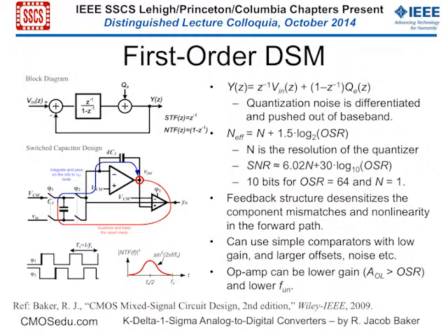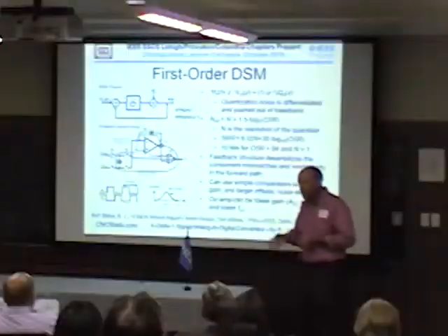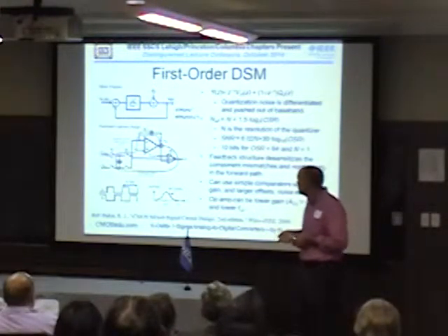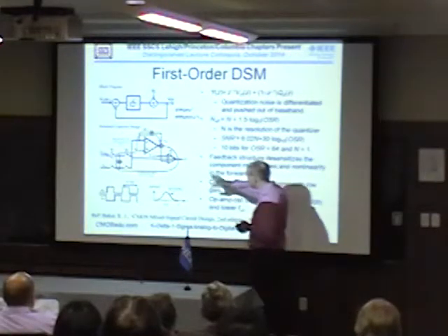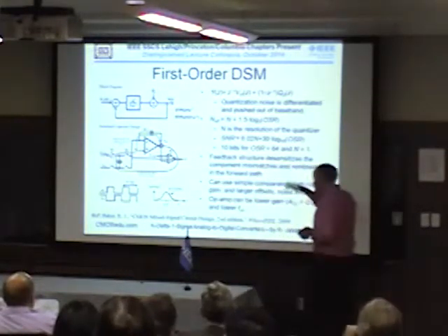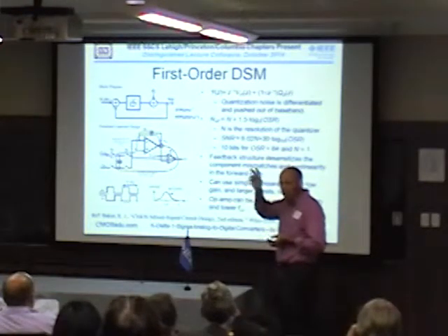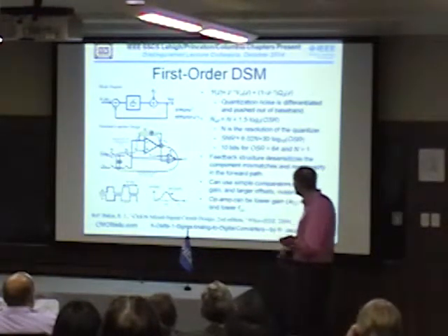And you could also do the analogy, if you wanted to be quicker, is you're going to either add a cup of water or you're going to remove a cup of water from the bucket. Okay, and so basically that's what this is. Okay, so your output code is 1010. You maybe change it to 2's complement for +1 and -1, a 0, 1, or a 1, 1. Feed it to the digital filter.